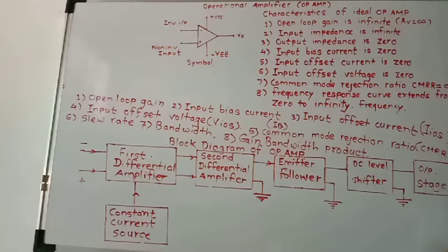It is normally a push-pull amplifier stage. Its output impedance is very low and it provides sufficient current to the load without distortion. It also helps to supply large output voltage without distortion. That is, it provides maximum current and maximum voltage without distortion.